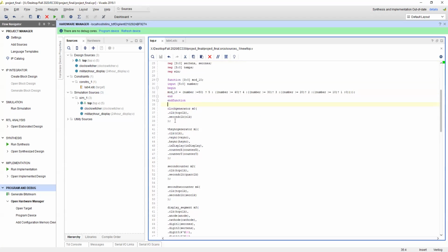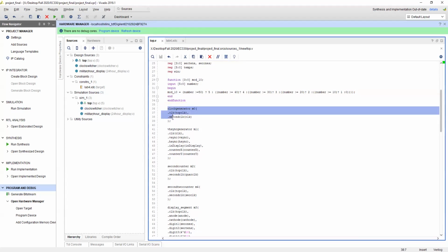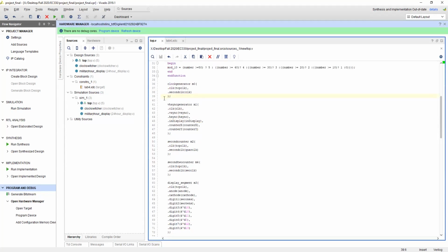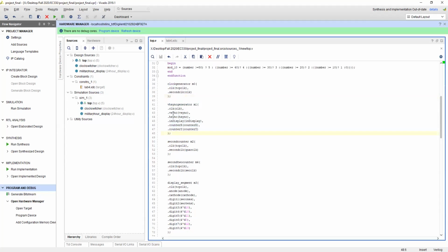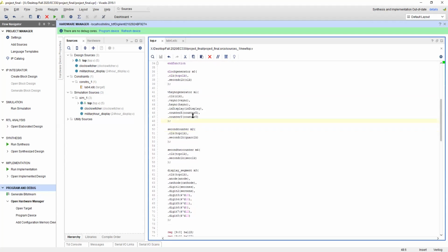We have multiple clock generators actually, but to begin with, this clock generator here is going to basically split up the top clock into the lower clock, and that lower clock is then used to run the entire VGA system. Here we have our VH sync generator, which we will talk more in depth about, but this uses that clock from the clock generator.